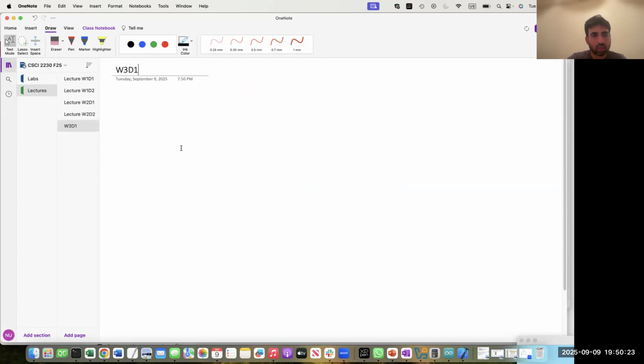So we have week 3, day 1, right? Okay, so let's say that you want to add two numbers, and both of them are 4-bit binary. I don't want to use 8-bit binary because then it will take time. So let's say I want to add 1 0 0 1 and 1 1 0 0. Here you will have 1 0 1, and when you add these two ones, what will be the value? 2, but we cannot write 2 in binary. The binary of 2 is 1 0, right? So we will write 0 here, and we will have a carry out which will be 1.